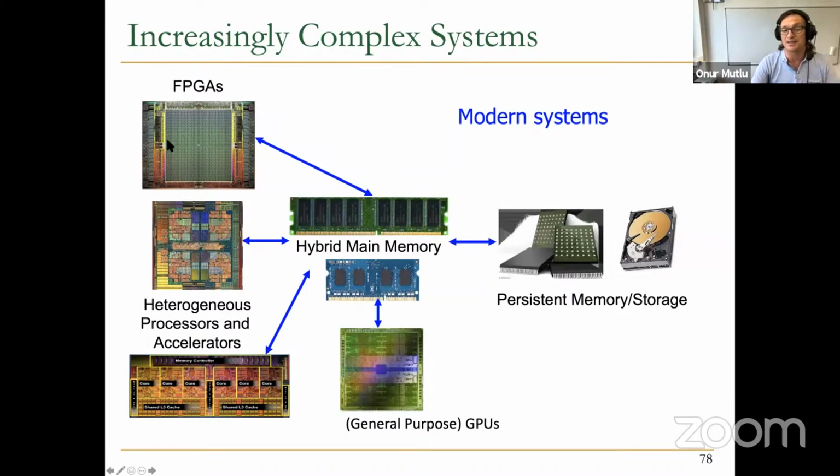But on top of that, we have separately FPGAs and maybe more powerful GPUs that you cannot fit on a single chip that is shared with the processor and other components that are also accessing the main memory. So we have heterogeneity at the chip scale, and we have heterogeneity across chips as well. And that's also happening inside the memory. You have heterogeneity across the memory hierarchy, and you have different types of memory. Even within the main memory, you may have a high bandwidth memory supplemented by a regular DRAM main memory that's not optimized for high bandwidth, for example. That's heterogeneous main memory for you, and that has been increasing more recently. GPUs are an example of this, but there are other systems like Intel's Knights Landing, I think they used to call it, which had a high bandwidth DRAM as well as a regular DRAM too.